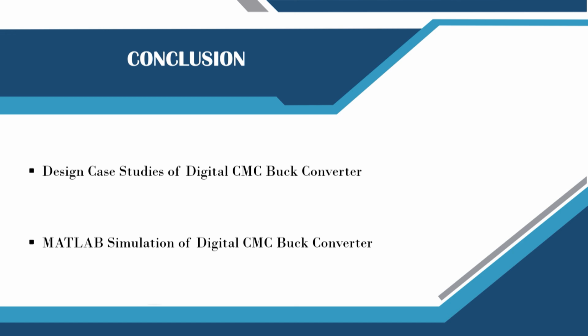So, in the subsequent lecture we will slowly tend towards the large signal based design and show that the performance can be much faster by utilizing the trajectory information as well as some advanced control algorithms. We can achieve a close to time optimal solution, and that is the future trend of digital control. But here we want to finish the small signal based design methodology.